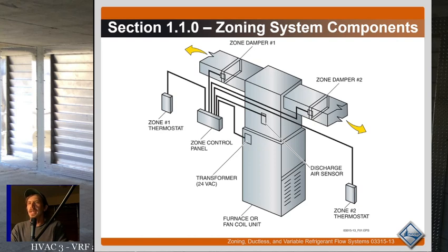It's basically just adding a bunch of automatically operated balancing dampers to the system for the most part that either open or close, and most of them have a minimum open position so that they're supplying some amount of air even if they're closed. It's just very small.